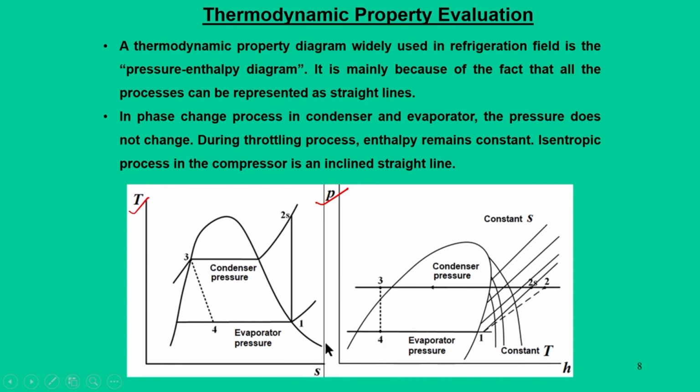And the other aspect is that when you deal with thermodynamic processes, the other important property that becomes vital is entropy, because a compression process, first thing we say, is an isentropic process, and also when you talk about throttling, enthalpy becomes a significant property, where enthalpy does not change. So, if you take all those parameters on their respective axes, then it becomes easy for us to locate the state points. That is the reason these two, temperature entropy and pressure enthalpy, are taken for discussion.